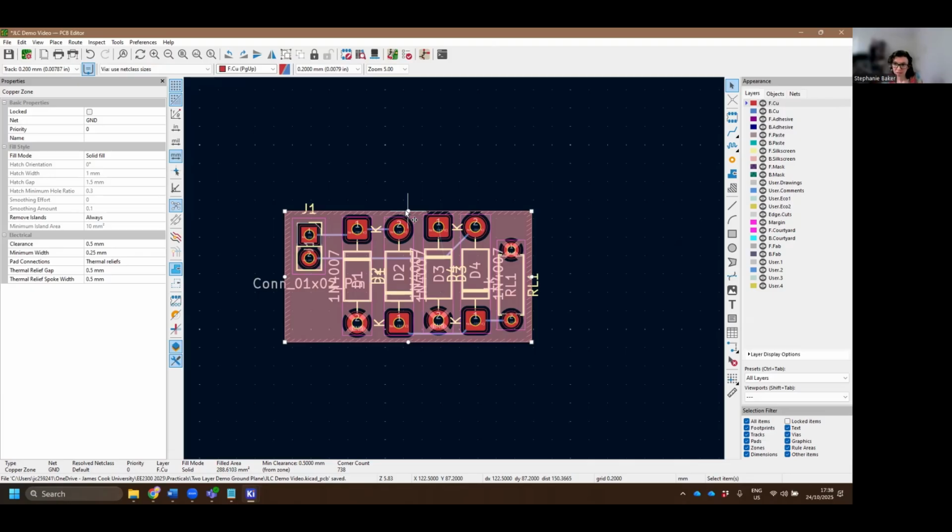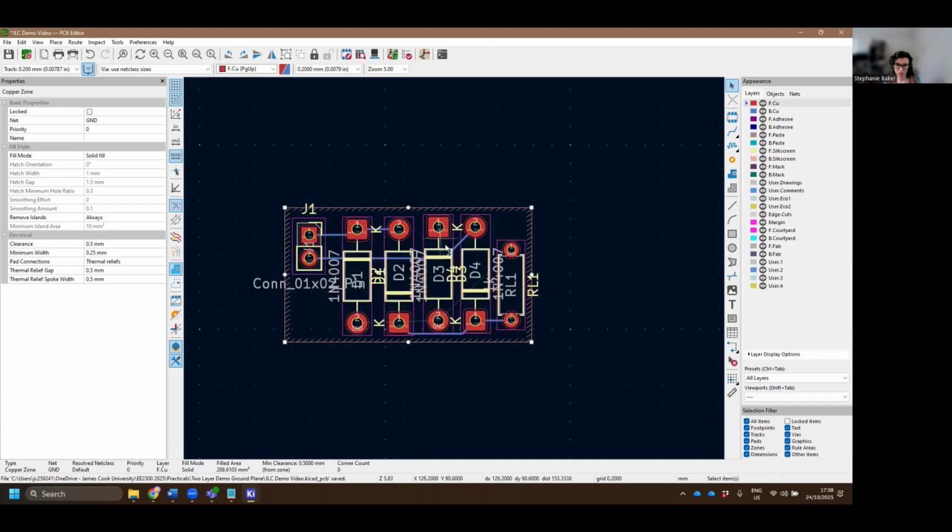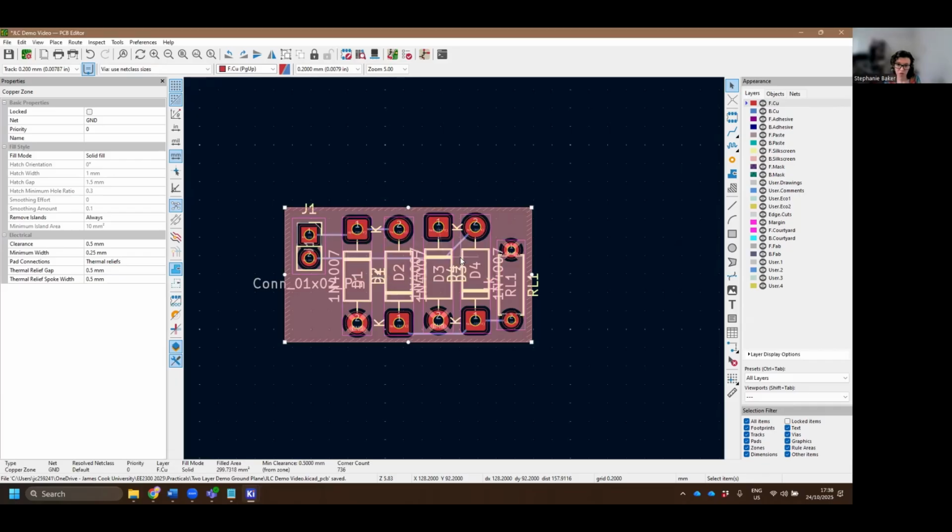Why would we want to do this? Well, if you've got an entire plane free, you might as well, because it's really good for signal integrity to have just a big empty piece of copper connecting all of your grounds together. So this is a really nice way to make use of a currently unused second layer. Like I said, it doesn't cost anything extra to do this. So I also probably made it a little bit too close to the top there by JLC's design rules. So I'm just going to move that out and fill it again. If you do change it, you do have to fill it again. Now that looks really good.